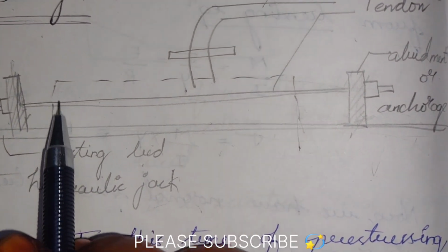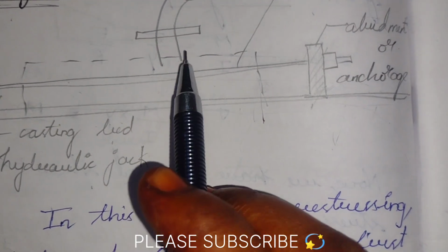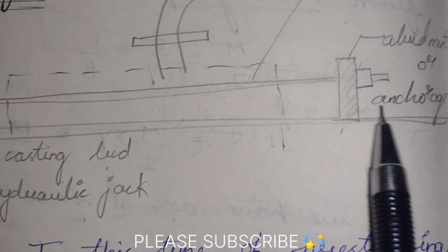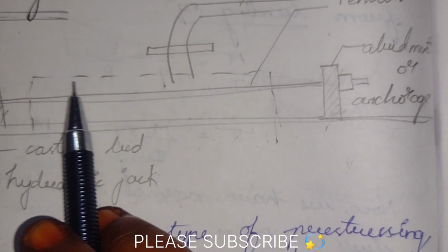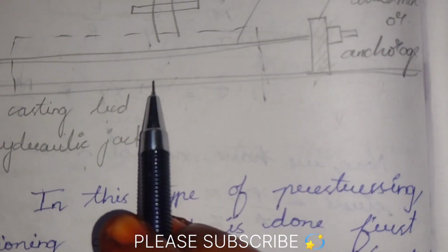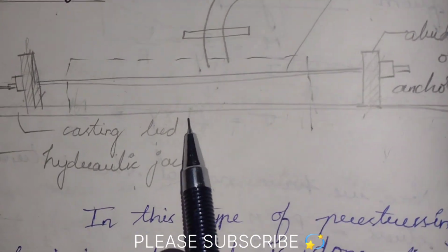So this is the mould. The dotted portion is the mould. This is the allowance given to pour the concrete. Before pouring the concrete itself, we are tensioning this wire, the tendon. This is the beam, this is the mould. First we are tensioning this, and after that we are pouring the concrete. This is the pre-tensioning system.